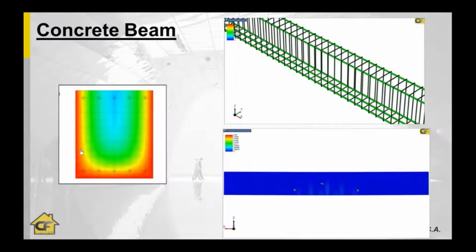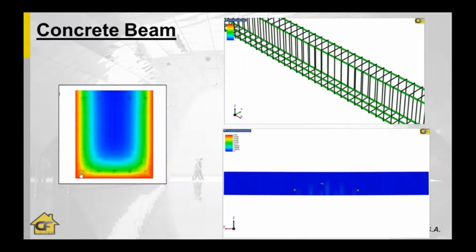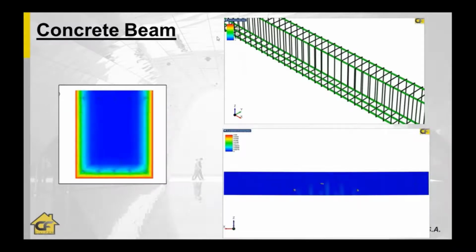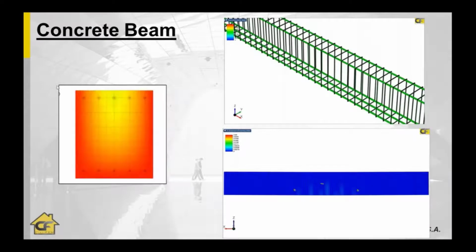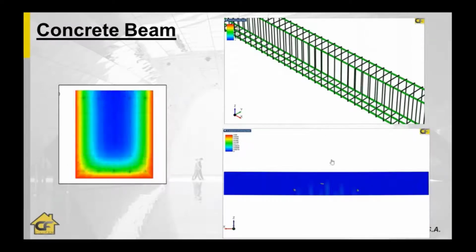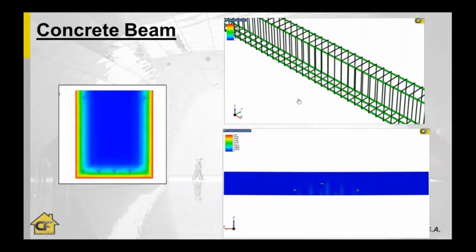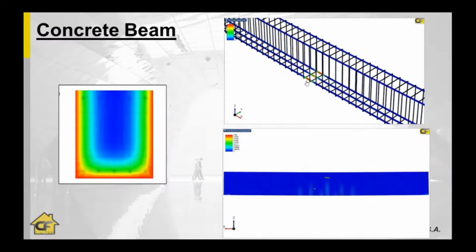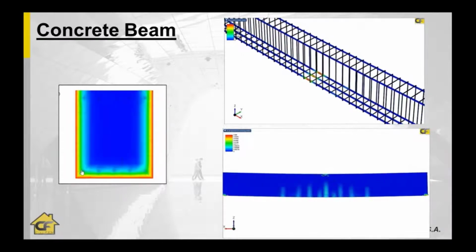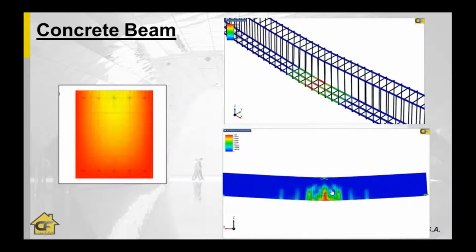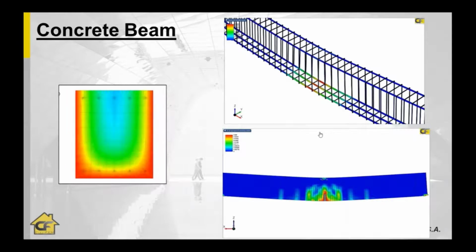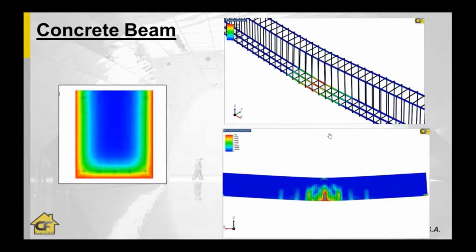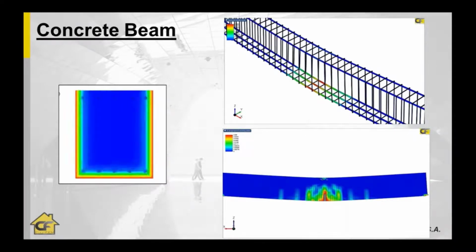And these are the thermal results for these elements, how the temperature goes inside the model. On top of this, there is no fire, it is only applied on lateral faces. And these are the results with the cracking and yielding on the model. So well, we can see that due to this fire, yielding starts happening on the model when temperature reaches the reinforcement, and cracking is also happening until collapse of the structure. So we obtain the time for collapsing this structure. It was about 210 minutes.